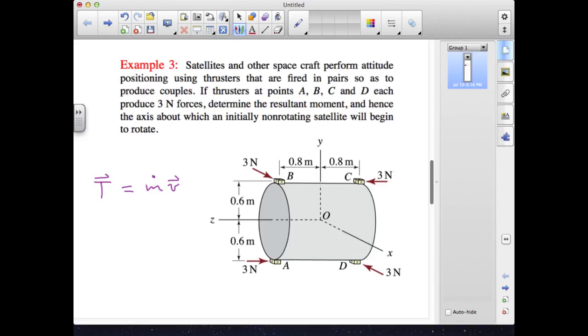The units will in fact give us a force, because m dot has units of, for instance, kilograms per second, and velocity has units of meters per second. The product gives kilogram meter per second squared, which is in fact newtons.